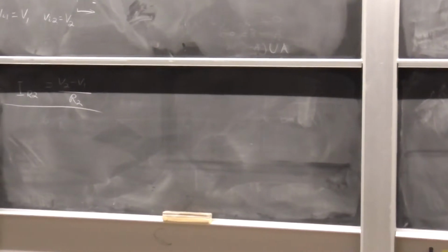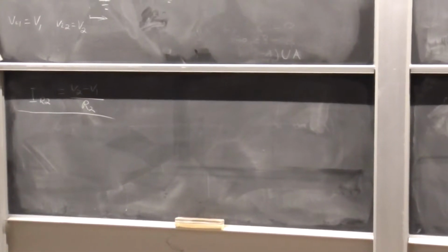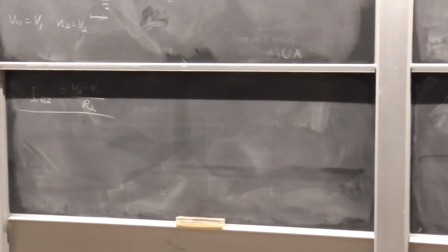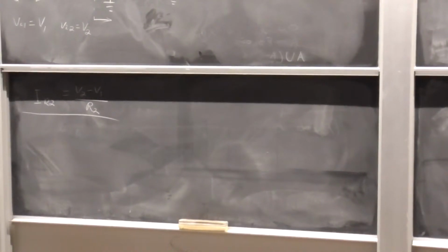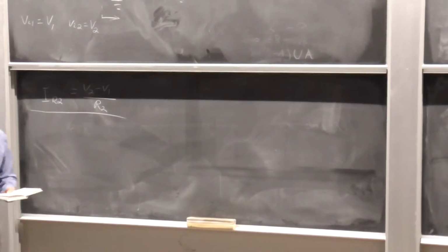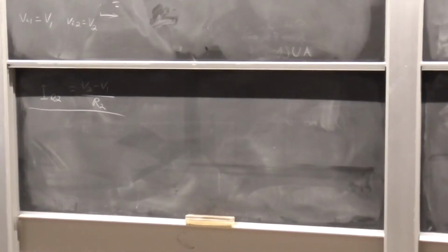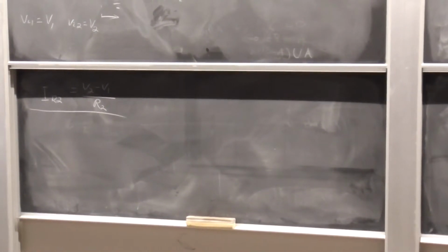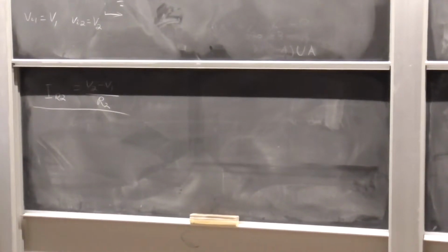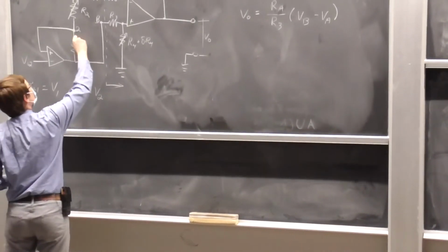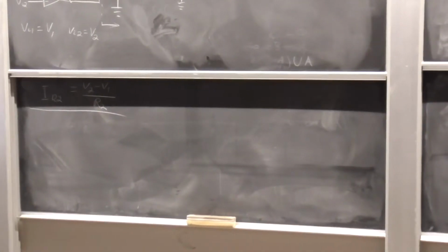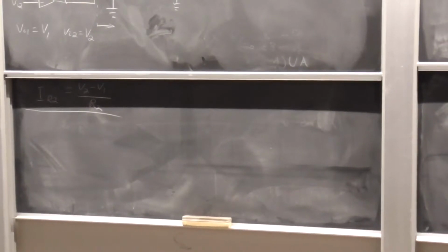So, now we pull in the operational amplifier law of current. How much current flows into the inputs of an operational amplifier in an ideal case? 0. 0! Yes, thank you. 0 the hero. So, we may therefore conclude that whatever current that's passing through R2 has nowhere to go except through either R1 resistor. There we go. Right?